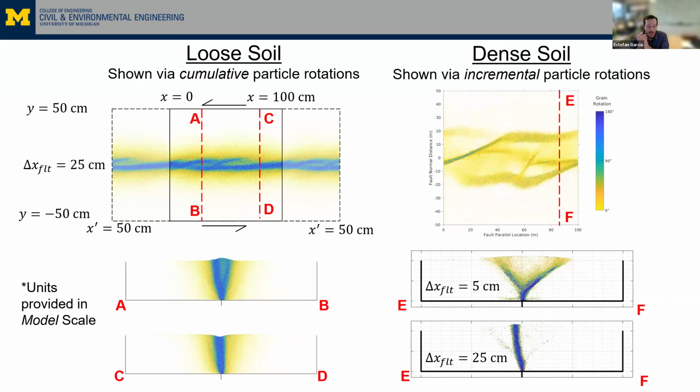And I'll note that the key features I want to point out are those that can be explained from observations at the smaller scale. For example, loose soils tend to have a contractive shear response in element scale simulations, such as in simple shear, and they tend to produce features such as ground surface subsidence. Yet also from reconnaissance investigations, such as what I showed from the previous Bray et al. work back in '94, we still tend to see these en echelon shears located along the surface trace of the fault, which tends to produce these regions of ground surface upheaval.